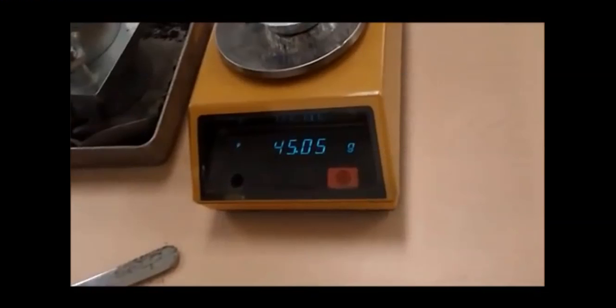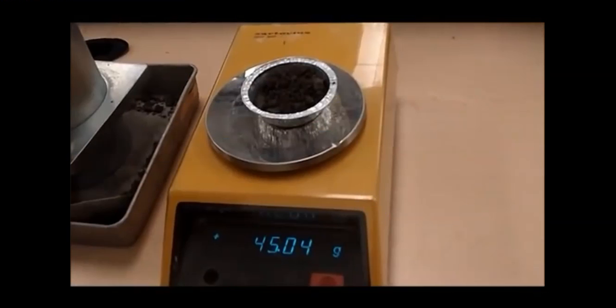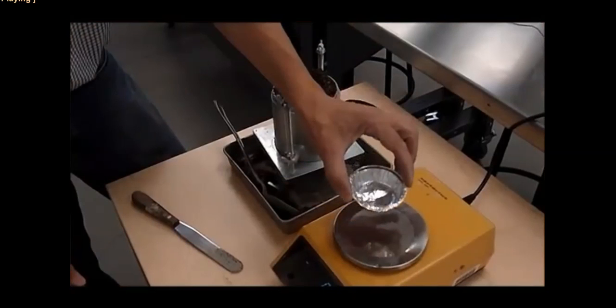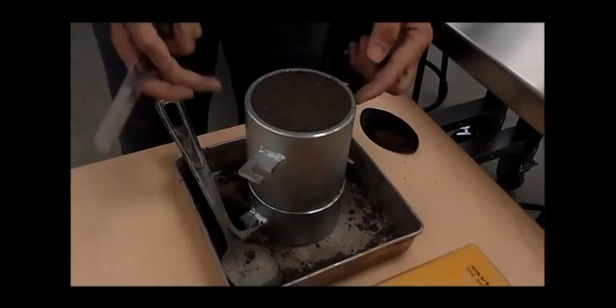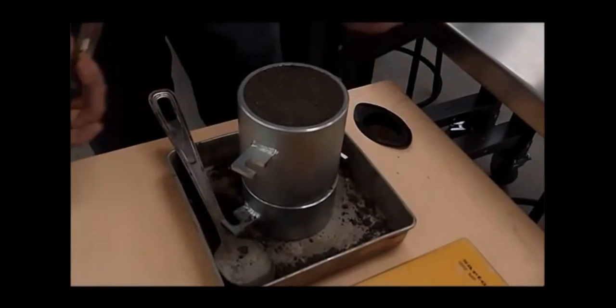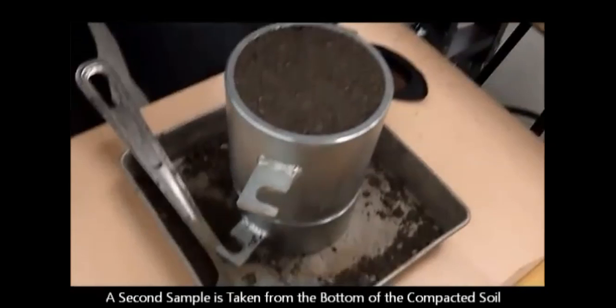So you know how to do water content determination using an oven. We'll take the weight of an empty container, and we'll take some moist or wet soil inside the container and again take the weight, and we'll keep this moist soil in the oven. So this is done 4 to 5 times. So we'll take out the soil from the mold and again we'll add 2% of water.